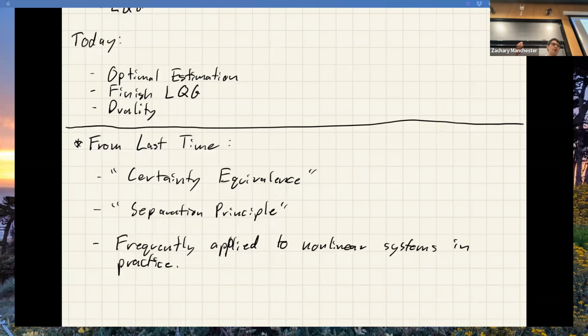And so what I would argue is, if you're in that scenario, the practical engineering answer is to put more sensors on your system so that your estimation problem's easier and you get a unimodal distribution, and then you can do this again. You probably don't want to be dealing with a multimodal state distribution. That is very scary.